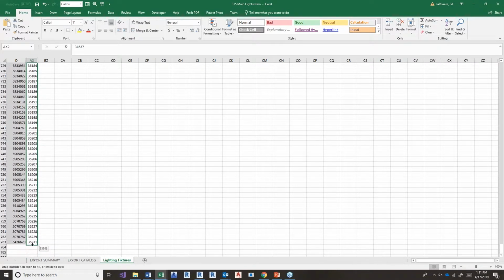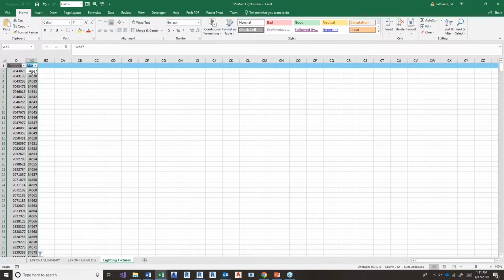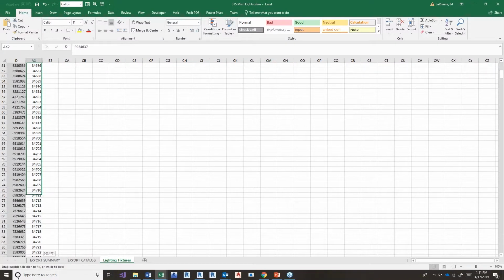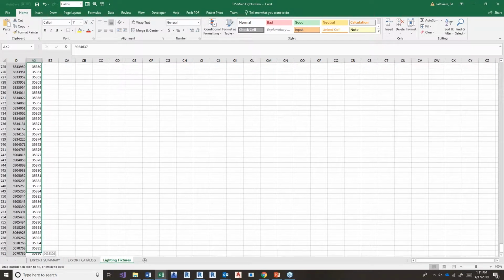And I'm going to drag the mark values all the way down to the bottom. And here now we've got a unique value. And maybe I've got some concern that 3, could that exist already in the project under some other element ID? Maybe I don't want to take a chance. So what I'm going to do is put a 9.9 at the very beginning of it. Stretch my column out just a little bit. Again, control, we'll drag everything down. We're almost done.